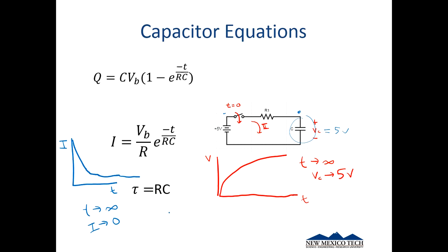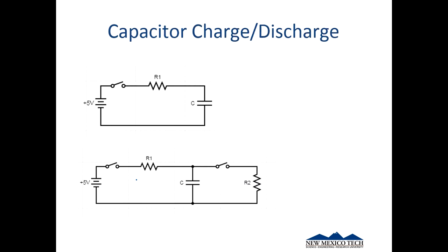And there's these equations. I have up here tau equals RC. This is what's known as the time constant, and you'll see it appear in these equations. It has to do with how fast this charges and how fast it discharges. You can do things based on time constants, like at 1 time constant this, 2 time constants this. Normally we say something like 5 time constants is as charged as we're going to be. So just a couple notes on that, and I did the charge cycle already, so I kind of covered that part.